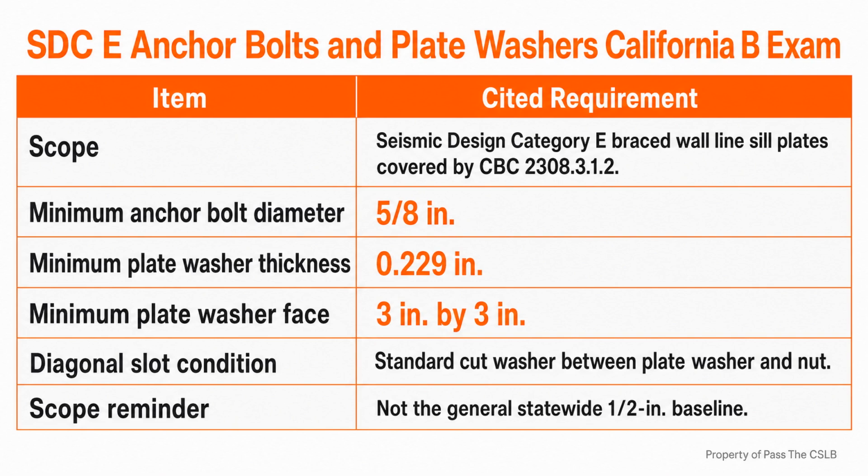correct later. Approved plans set the general boundary, California Administrative Code, Section 4-3.4.3, subsection A, supports the duty to complete the work in accordance with approved plans. For seismic hardware, that means I do not substitute a connector, change a fastener schedule, relocate a hold down, or alter a structural dimension based only on field judgment.